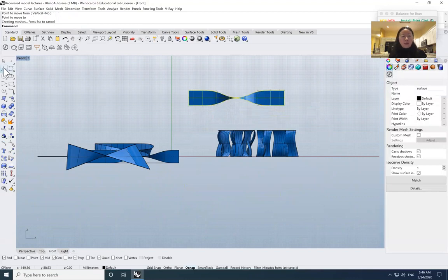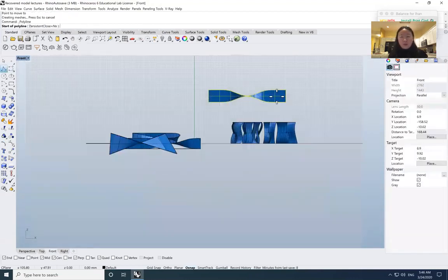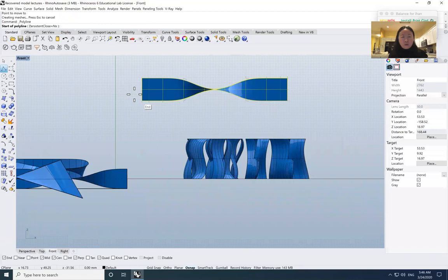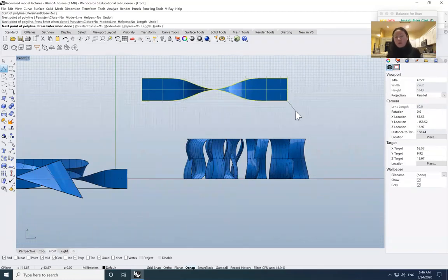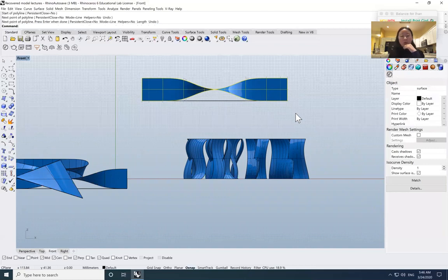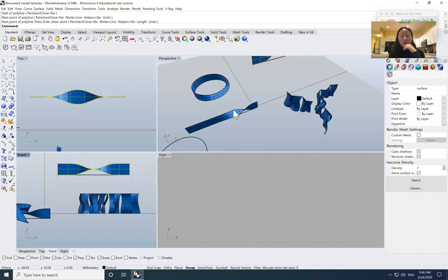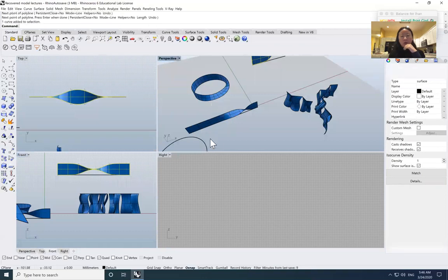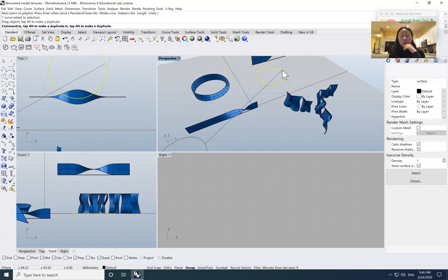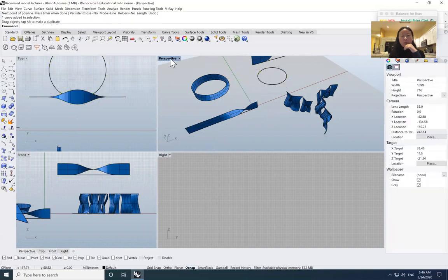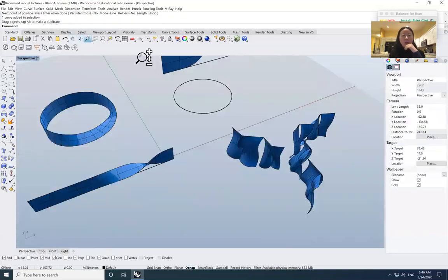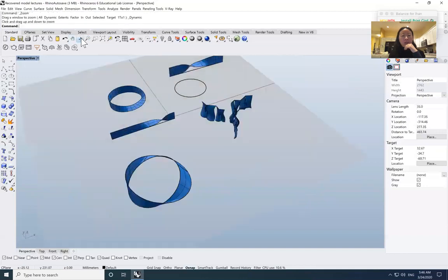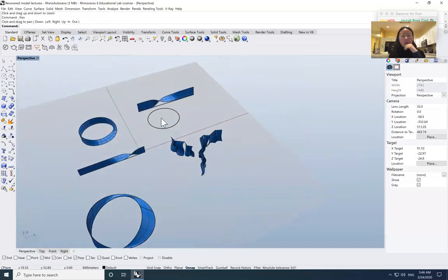And I'm going to draw a line based on the bottom of the shape. So what I'm going to do is flow. This time it's not a flow along surface, it's a flow from a line into a circle. So using the line as the base, and then flow it onto the circle.